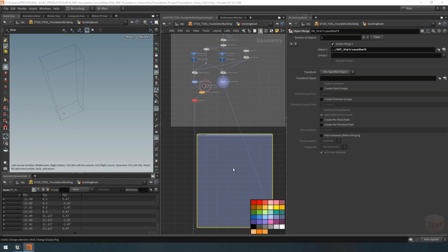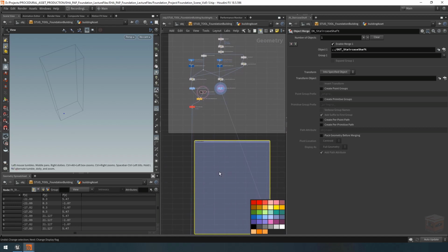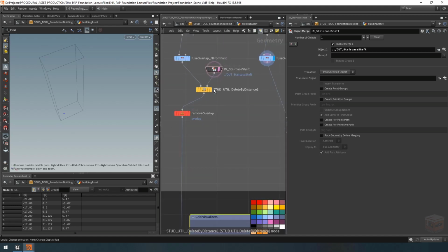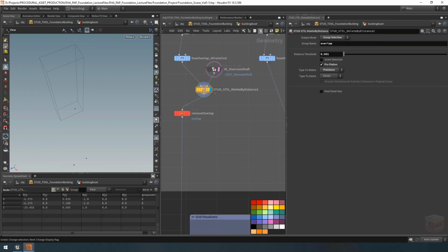Then, the first thing that I would like to do is create an arrow object that we can use to visualize our different points. Because right now we have our points, and they have a normal. In this case, we also have our overlap group on it as well. I want to make sure that we can visualize this with a mesh, because we cannot actually view these points in Unreal, right? We need a mesh for that.